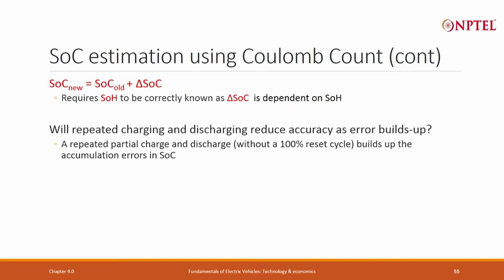And so, this method depends on the initial value and SOH value, all of that are changing. So, you can use it for a short period of time. You have to reset and recalibrate the battery after that time. So, this is an involved process which a battery designer actually have to do using the BMS algorithm, and this is where most people do not design good batteries. In lead acid, this was not there.